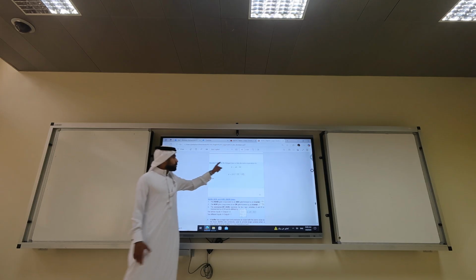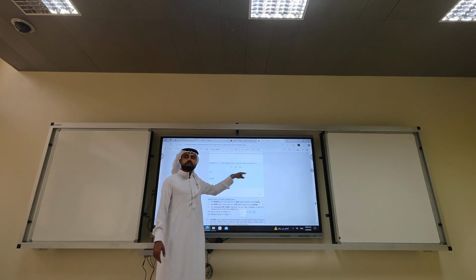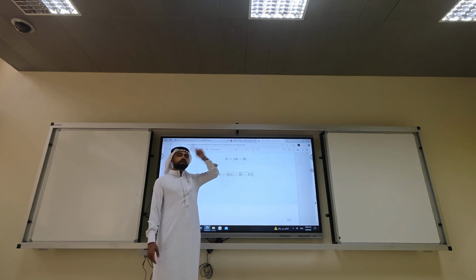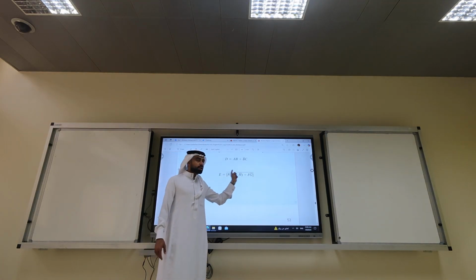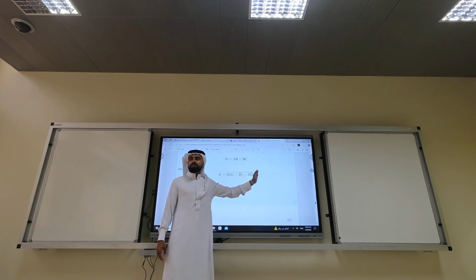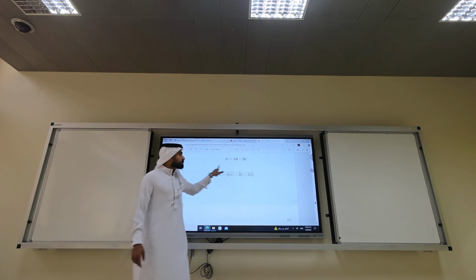Don't forget, in De Morgan's law, if you see a big bar across the whole thing, what will happen? The big bar you add at the end will cancel only the big bar. Half bar, will it cancel it? We don't care. 75% of the terms have a bar, but the last one doesn't have a bar. The big bar will cancel it. So don't make a mess. Remember the 3 steps?